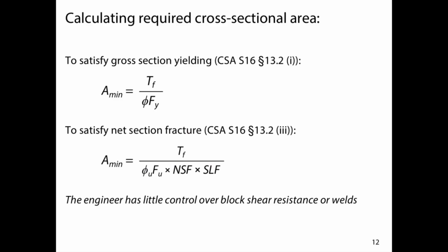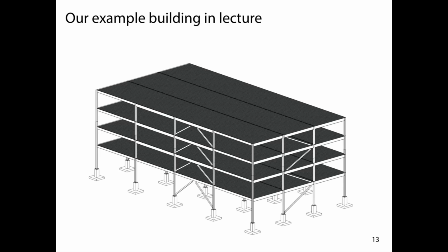So if we're coming back to our example building here, we already designed this brace down here for a certain force. We designed this as a bolted connection. We looked at a flat bar in class. The flat bar is pretty big. I probably wouldn't recommend using that flat bar in an actual practical application. But you could use a WT or something else, and a WT is selected in the example notes as an alternative.